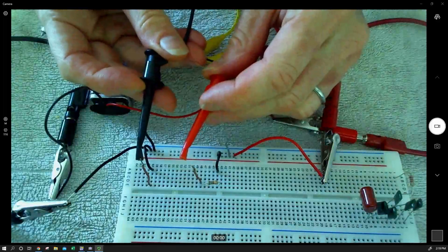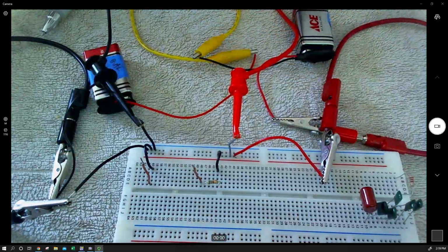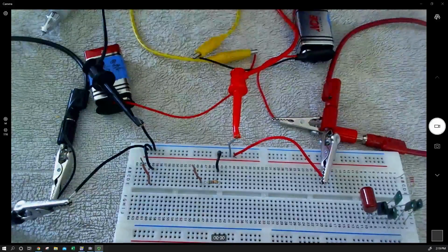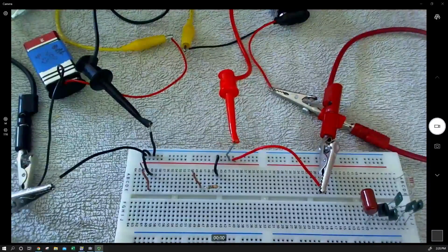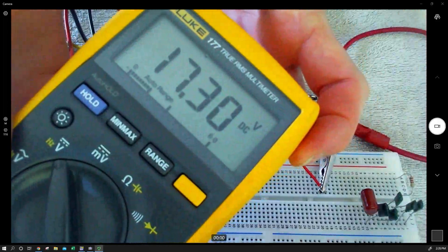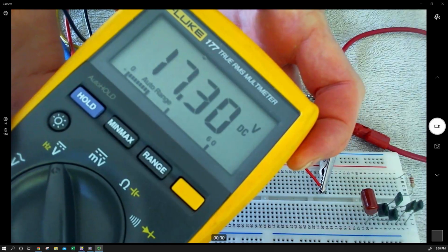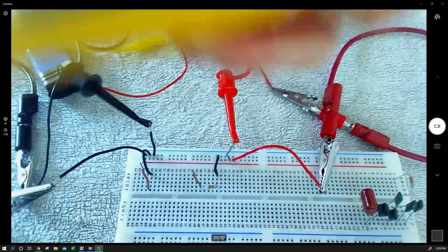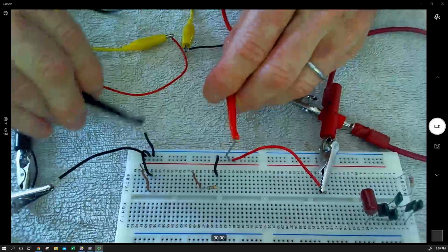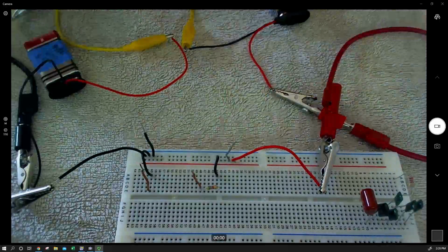circuit. The circuit is open here. So if I use my measurement points, I am getting basically what I would expect, the two open circuit voltages added. So 8.63 times 2 within meter error. So I now have 17 volts that I can drive the circuit with. And again, I have a fairly high resistance in the load itself.